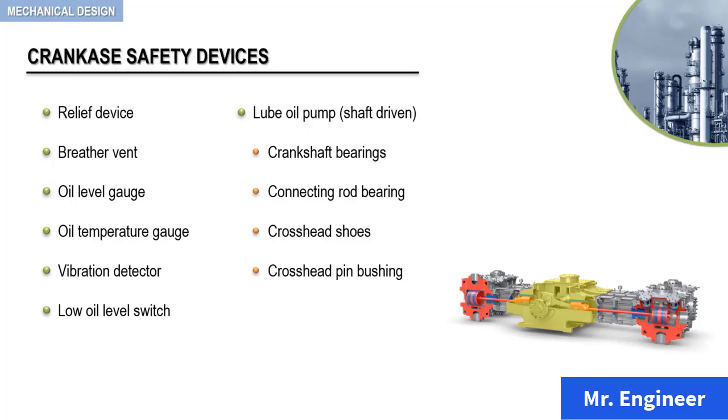Now, an important reliability consideration is to make sure that the crankcase is securely mounted and level. This requires proper grounding and maintaining a crack-free base support. Since the dynamic forces on the crankcase and crosshead mounting feet can be very large, it is common to use an epoxy grout.